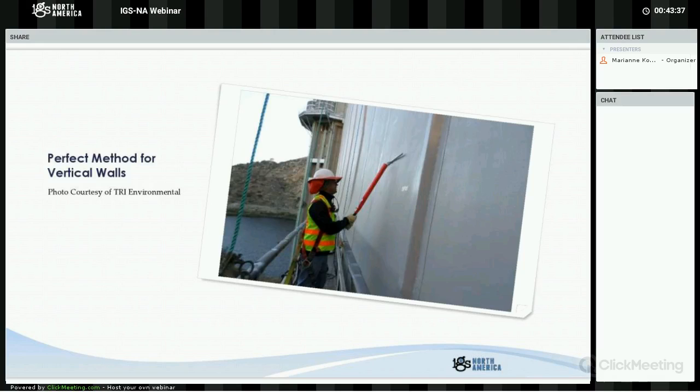So this equipment in this photo is grounded to the concrete structure below the facing of the dam. It's just tied around a bolt and then taped. And so if there's any leaks in this geomembrane facing, you'll get that electrical arc right through the geomembrane.